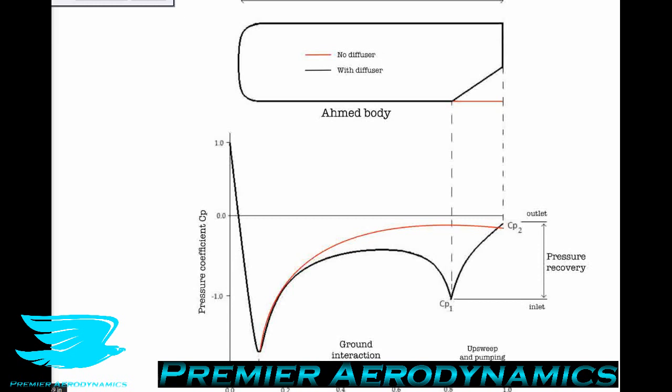And the reason why it is important to match the free stream pressure is because if there's a lower pressure, then that means that some portion of the rear of the car is experiencing a lower pressure, and that is more drag. What we just went through here, again, assumes largely that the air enters the underbody section